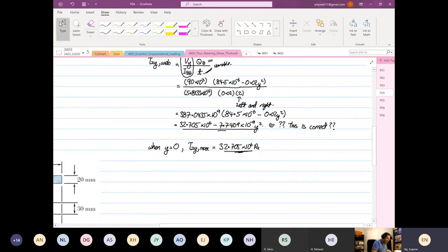You cannot have that explanation now, because if we were to sketch the profile out, right? So if this is your shear, this is your y, this is your flange. Because of the thickness change, the web stress will increase and then come back down here. This is how your profile looks like. So your statement that you just made regarding half of it is not valid. You see why now? Yes or no? Yeah. Okay. Good try though.